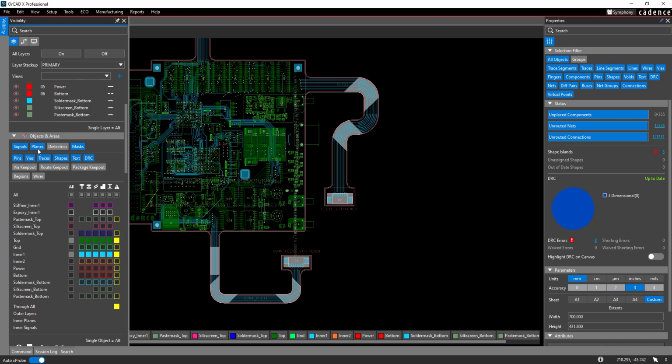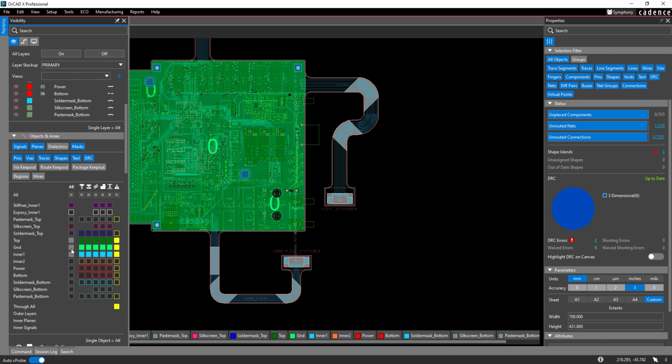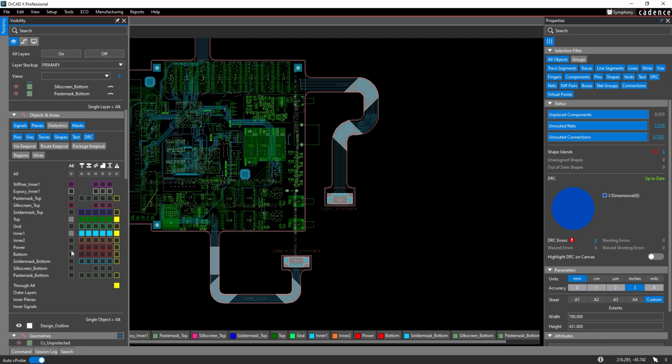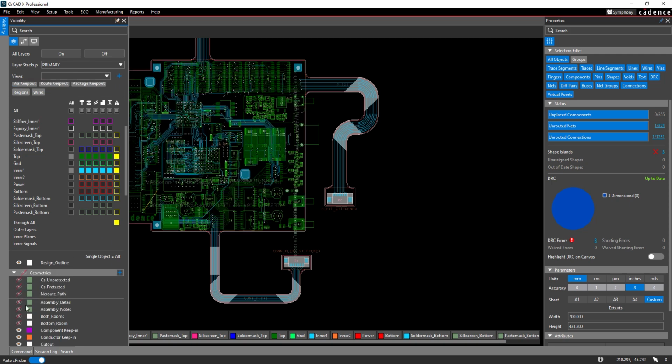Lists of board layers and other objects are shown. To enable or disable a board layer, select the space under All to turn the layer on or off. To enable or disable another object, select the eye icon for that object. The layer visibility panel can be used to improve visibility when designing a crowded board with components on both sides.